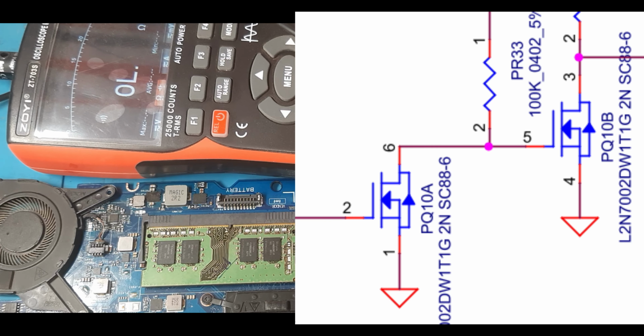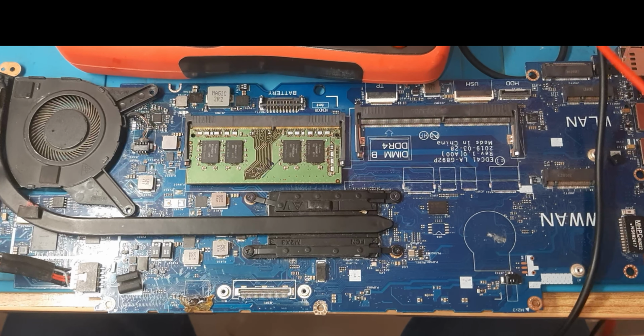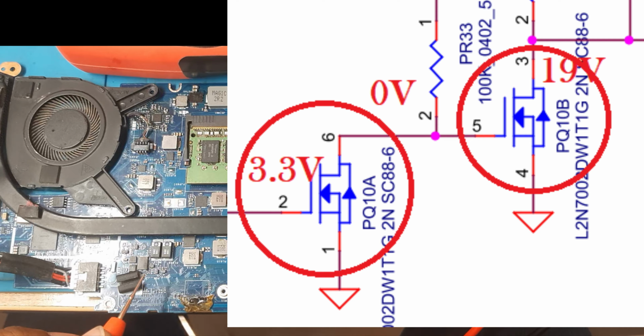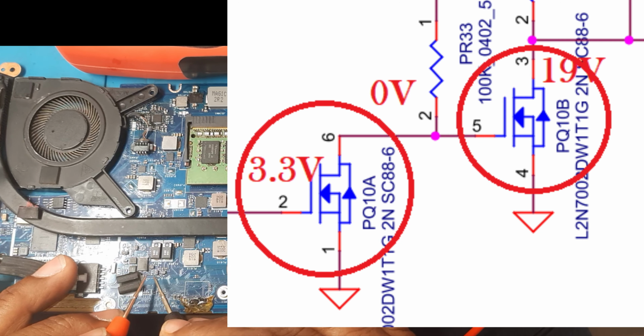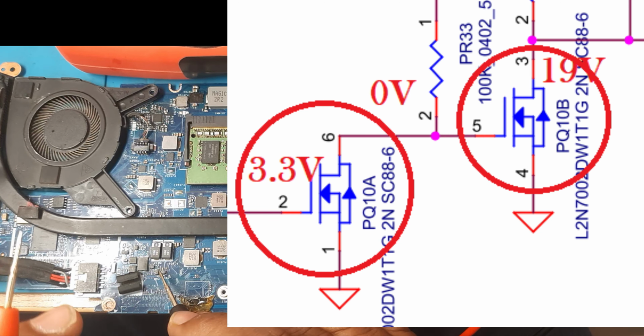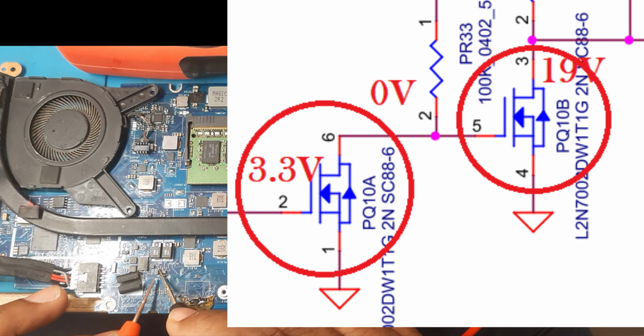This is a 6 leg MOSFET, a dual N channel MOSFET. Okay, it is connected for the protection IC. This is actually the protection IC. So using this only, the 19 volt supply will be released. According to the logic, it's pin number 2. If it receives voltage, then almost all except pin 3 will be ground. Okay, that is the logic here, if pin number 2 receives voltage.